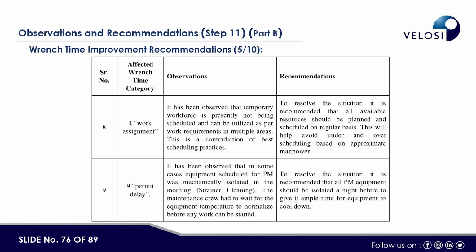It should be improved. It has been observed that in some cases, equipment scheduled for PM was mechanically isolated in the morning for strainer cleaning. The maintenance crew had to wait for the equipment temperature to normalize before it could start the work. It means the planning part was missing.